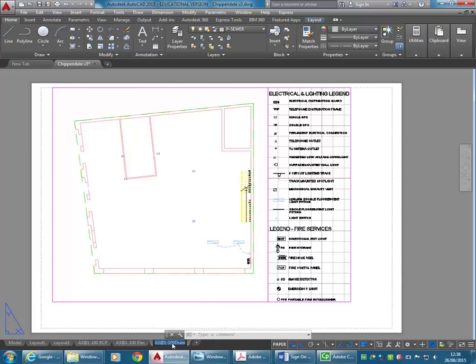It could just go on the reflective ceiling plan, but otherwise you'd need a separate drawing for that as well. Oh no, actually, sorry, you could definitely show the location of the sprinklers on the drainage diagram. But usually that's just done for buildings that have those. They're normally fairly large commercial buildings, and so you'll do a dedicated reflective ceiling plan that will show all of the services. And there are a lot of other services you'll have in a building like that that you wouldn't have in a building like this.